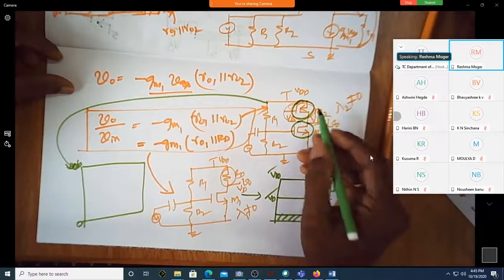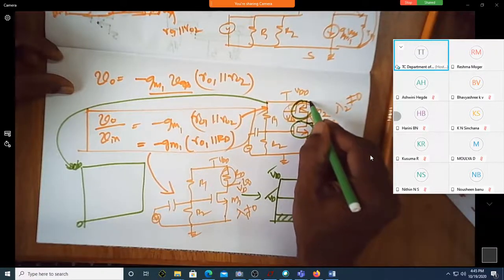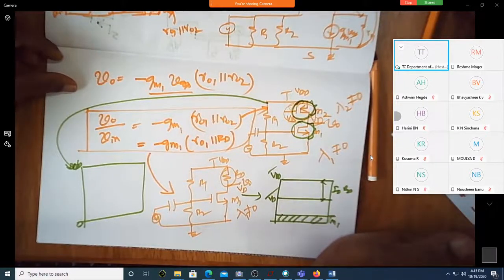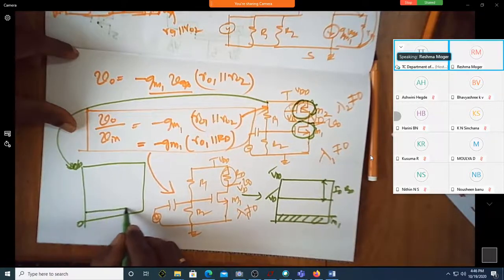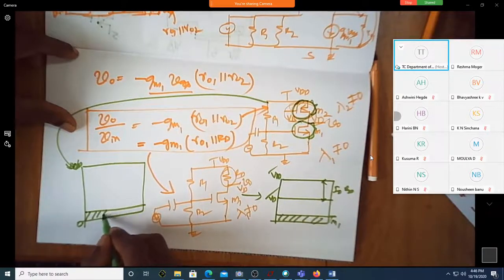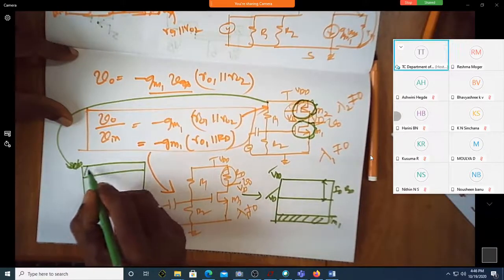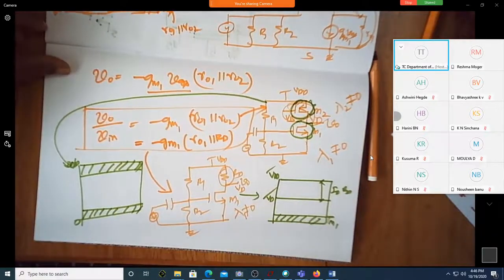So do we need to keep some voltage to keep it in saturation and some minimum voltage to keep the other transistor also in saturation? So shall I dedicate some voltage over here to keep the MOSFET in saturation so that I cannot enter the triode region? Can I dedicate the same voltage on the other side so that I can keep both the MOSFETs in saturation?